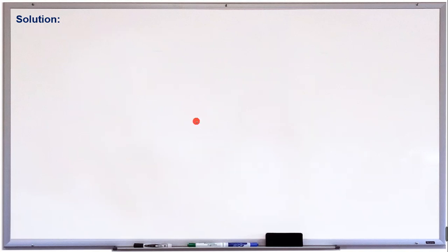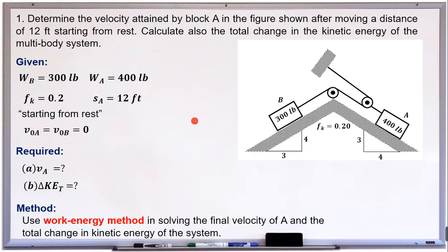It is because, from the previous slide, the weight of block B is great, although in numerical value it is not greater than A. Since we have an inclination here, and since we have a compound pulley right here, if this is 400 pounds, most likely the horizontal component of the weight for block A is a little bit smaller than 400 pounds.